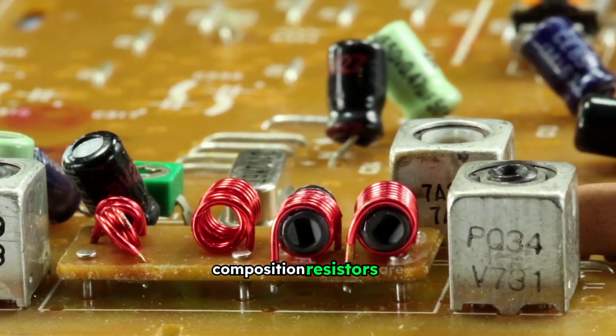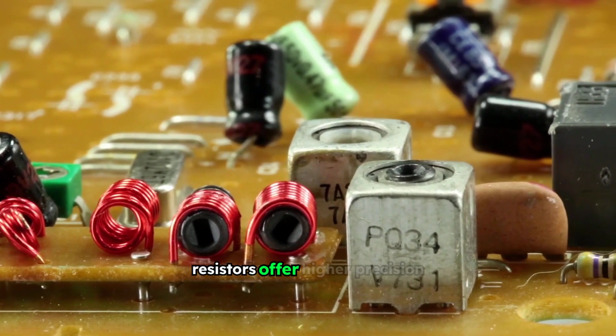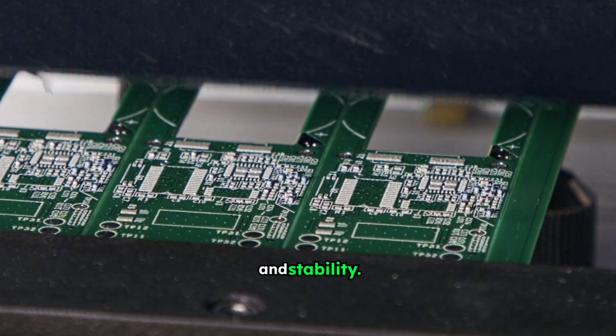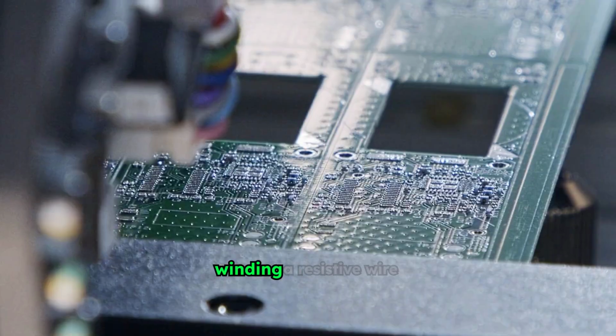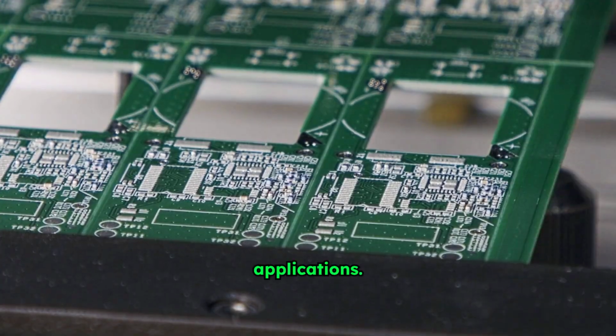Carbon composition resistors are inexpensive, but have lower precision. Metal film resistors offer higher precision and stability. Wire wound resistors are made by winding a resistive wire around a non-conductive core, suitable for high-power applications.